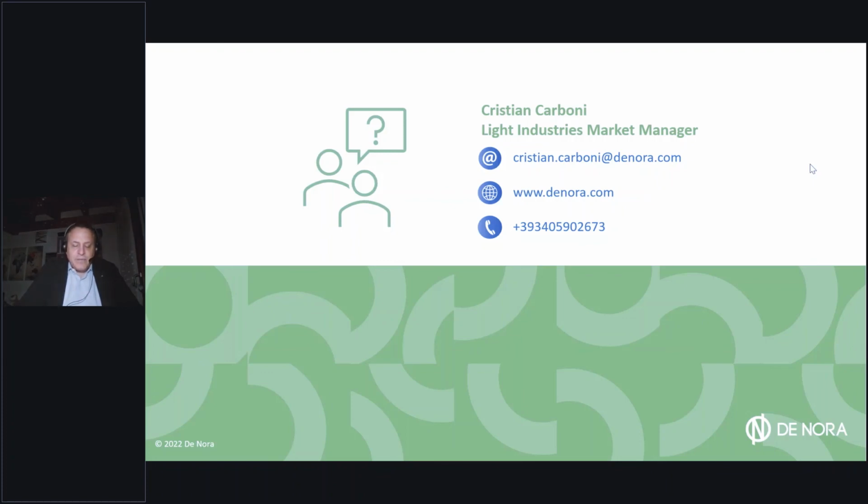This is the reason why in some slides I showed you 0.3 ppm during the night, and 0.1 or 0.05 during the day. Sure, it is better to have a stable ozone level, for example 0.3, but if people go inside a storage room, we need to turn off the ozone generation during the day to avoid safety problems.